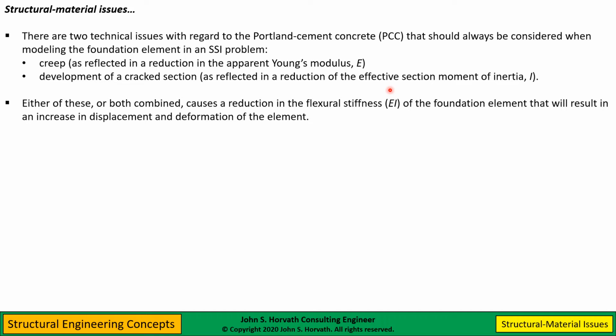In general, the more flexible, for example, a mat foundation or a slab or some sort of structural element, the more displacement and deformation we will have to the overall structure. The point I'm trying to emphasize here is we do not want to overestimate the stiffness of the structural element, whether it's the mat foundation or slab or whatever. We want to consider shear effects, creep of the concrete, cracked section behavior.